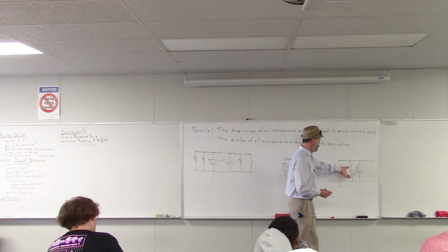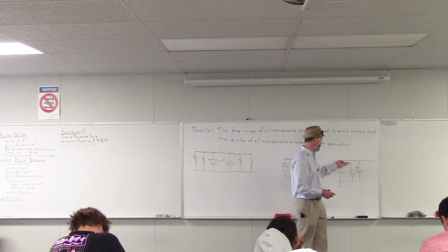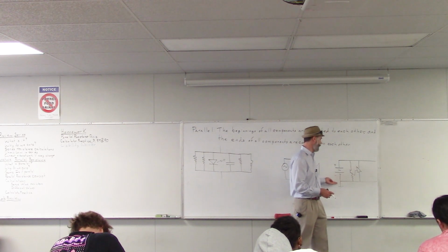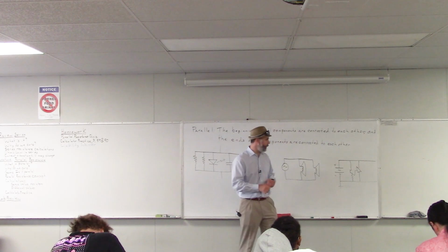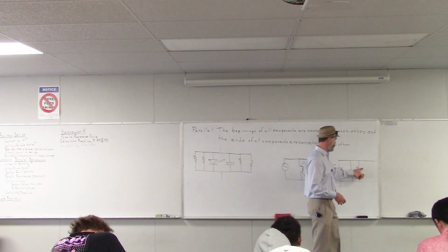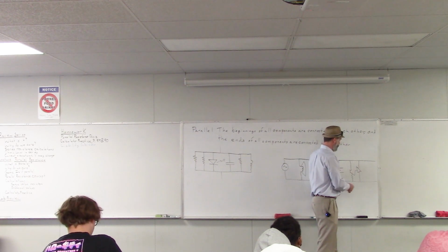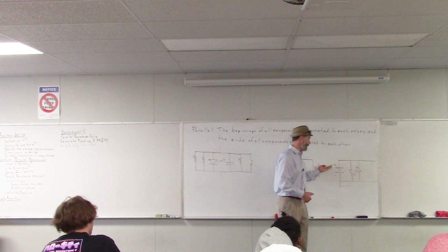And basically, each one of these sections draws power from the power side and returns the electricity to ground. And so anytime you need a new section in your circuit that needs power, you just put it in parallel like this, and it draws power and ground from your power supply.